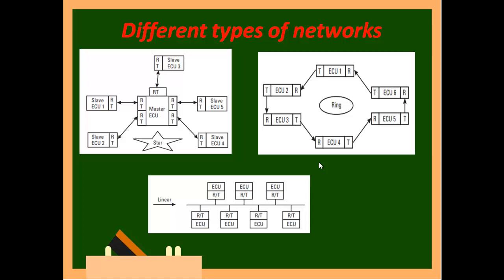The first one you have seen is master-slave, where only the master can communicate. A slave cannot communicate directly with another slave. It had one difficulty: slave to slave communication is not possible. When you come to ring, there is no such master, everybody is connected, so that master problem is overcome, but if anyone fails, that's all, the ring is open and communication will not reach everyone. Taking these two into account, I'm bringing in linear, where everybody is connected. Whoever wants to be master can be master and can communicate with anyone, and vice versa is possible.